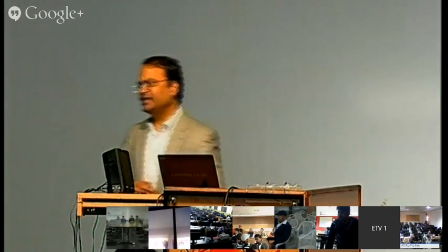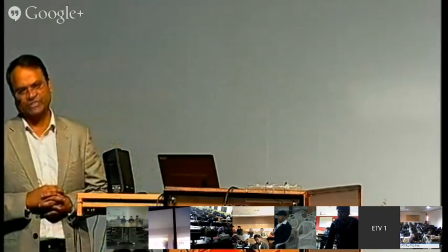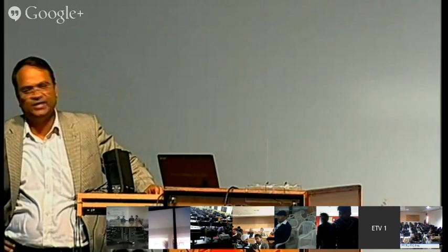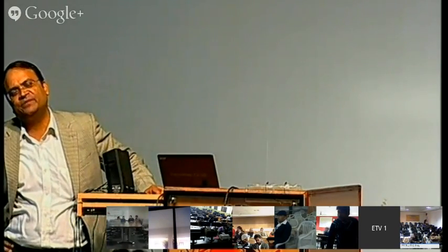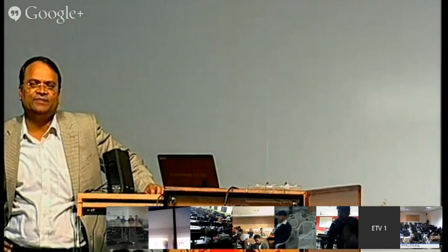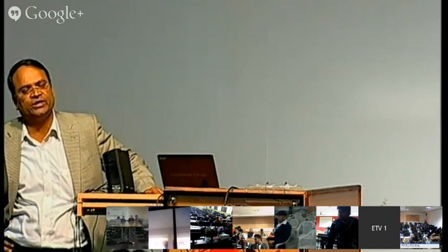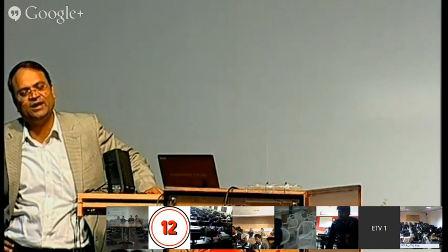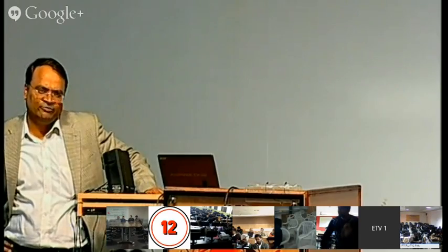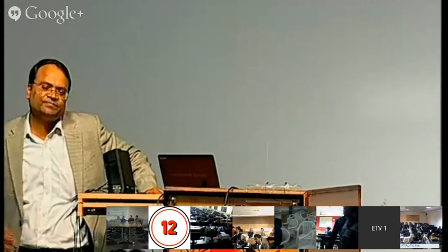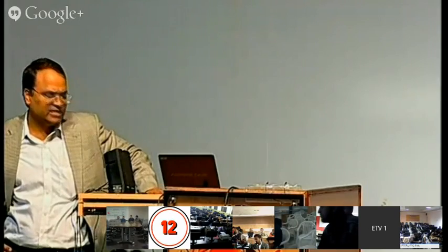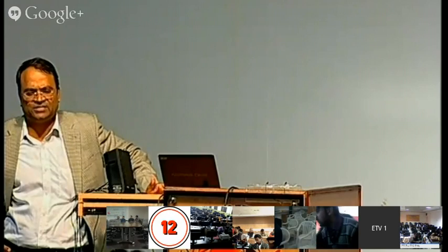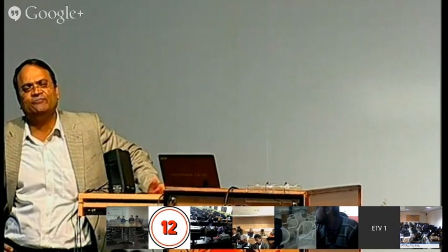My understanding is that friction is the main nuisance. If we are mitigating or minimizing the friction, then it is fine, because the main wear is happening because of the friction. When we mitigate friction, we are replacing solid friction or dry friction by fluid friction. If fluid is coming at the interface, fluid friction is less and a film is there, so wear won't take place, or very small wear will take place. So life will be longer.